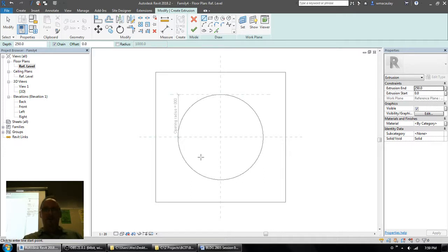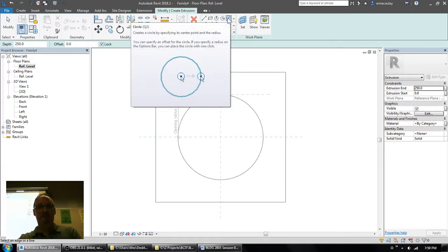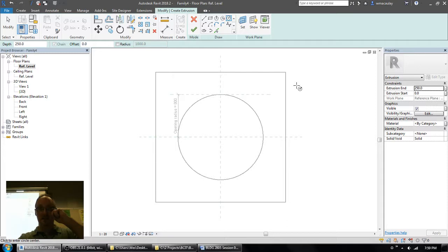Now, try as you might. If you folks remember when we had the opening tool in that window, when we're building an extrusion, we could use the pick tool and we could simply pick the edge of the opening. You folks can see that is not going to work. See, pick tool on, lock option here. I got nothing. So what that means is we'll just have to draw the circles ourselves. So can't use the pick tool, just got to draw with the circle tool.